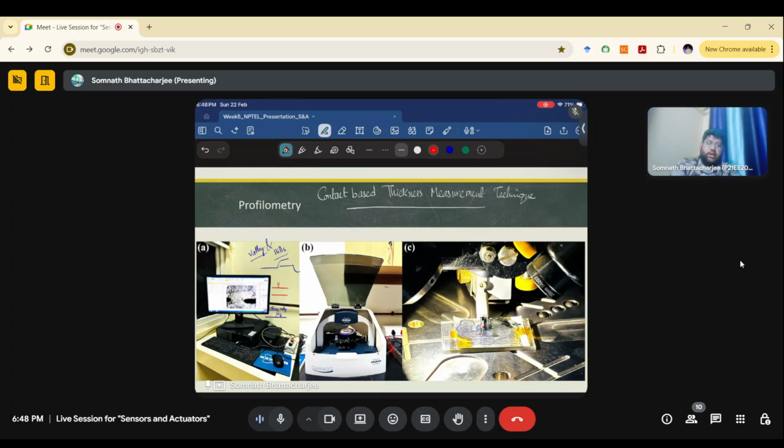In my devices the thickness is about 500 to 600 nanometers, and it can measure that very finely, but it won't easily detect a 1 nanometer or 5 nanometer difference. Because of that, what I have been doing is taking several data points from different positions. Let's say we put the tip here, and here, like that. From 15 to 20 different data points, we take the average, and based on that we state this is the basic thickness, the mean thickness.